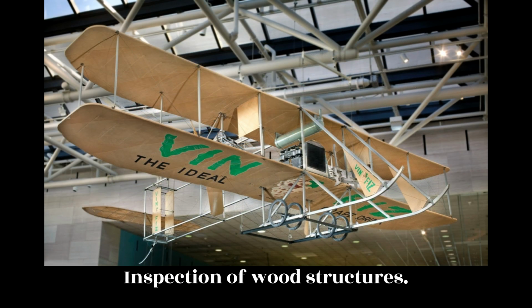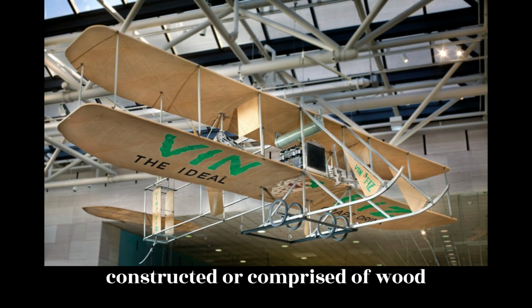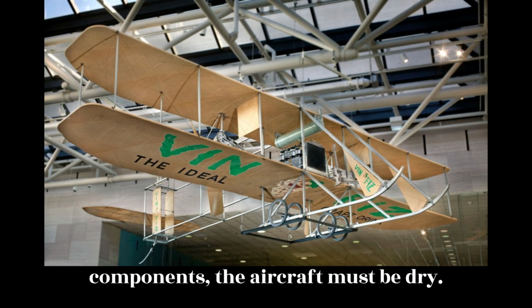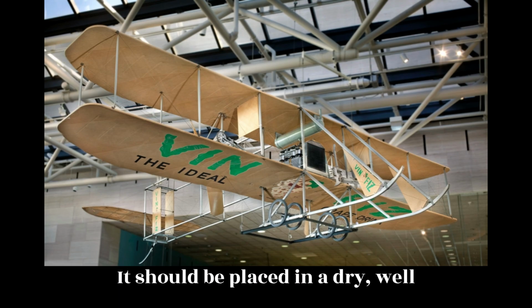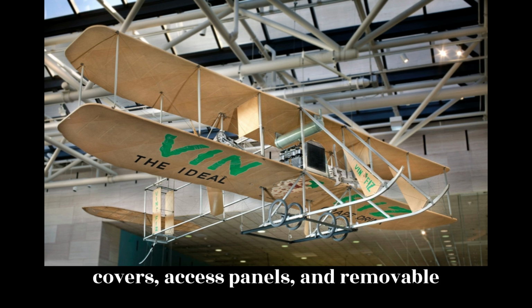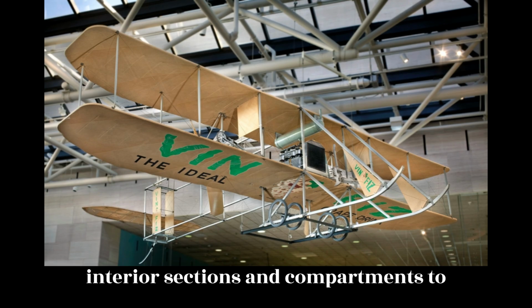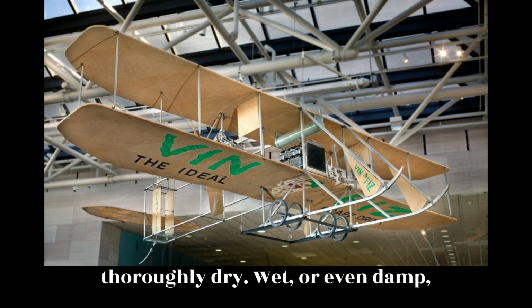Inspection of wood structures. To properly inspect an aircraft constructed or comprised of wood components, the aircraft must be dry. It should be placed in a dry, well-ventilated hangar with all inspection covers, access panels, and removable fairings opened and removed. This allows interior sections and compartments to thoroughly dry.